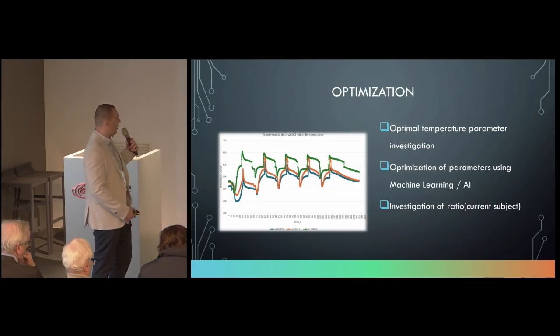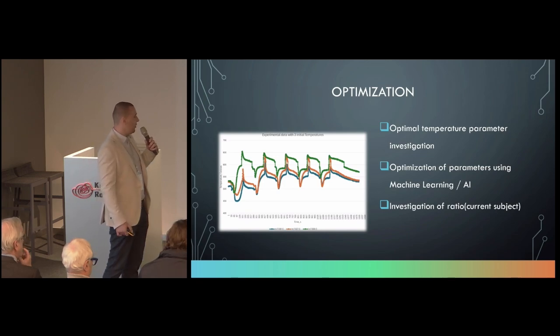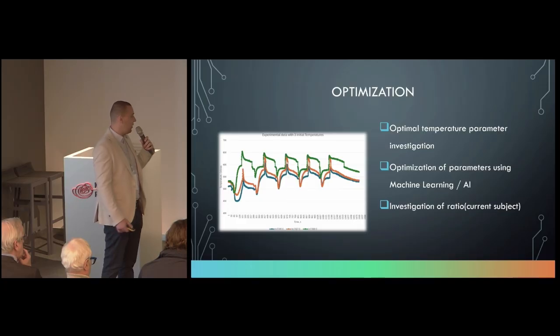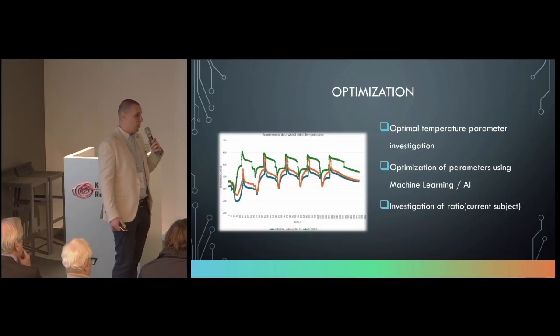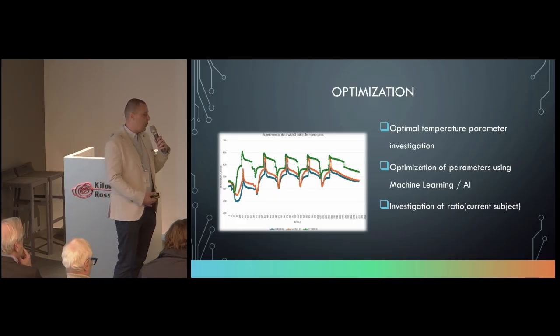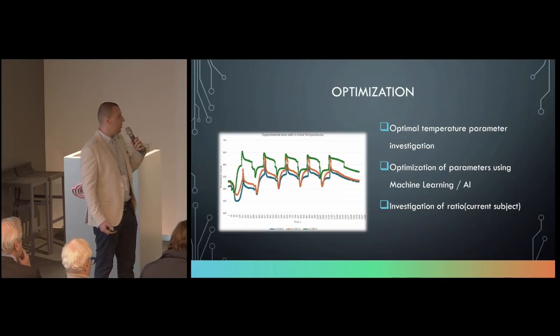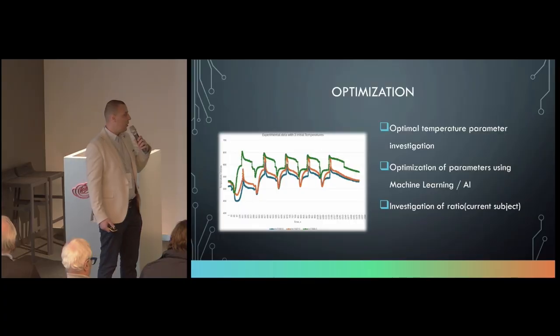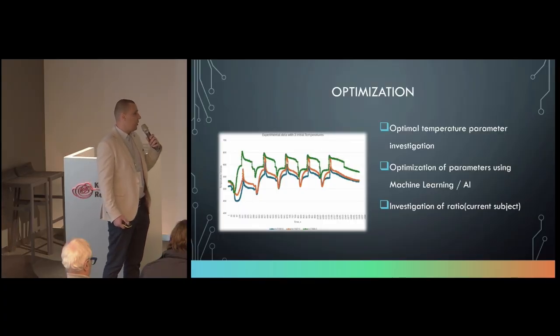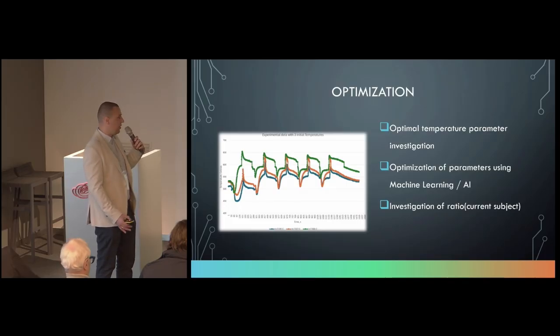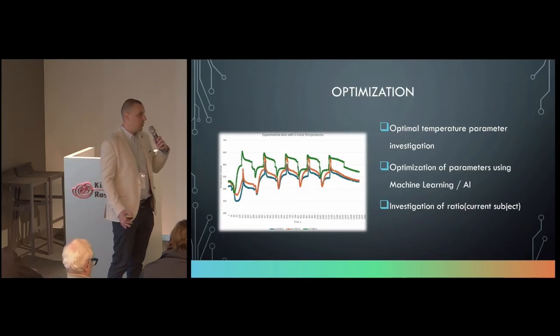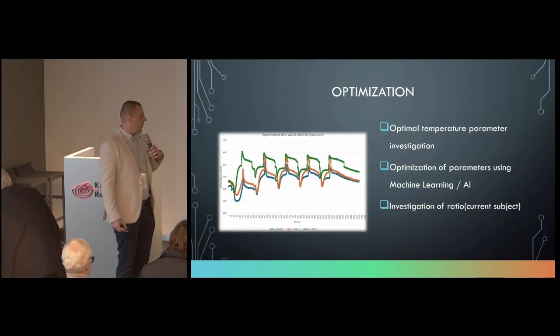You can see the temperature experiment we have done with three initial temperatures of 510, 527, and 535 degrees Celsius. Again, that's the temperature of the whole specimen. The temperature of the constantan wire is around 670 degrees, between that and 700, and up to 950 when we want to break stuff.